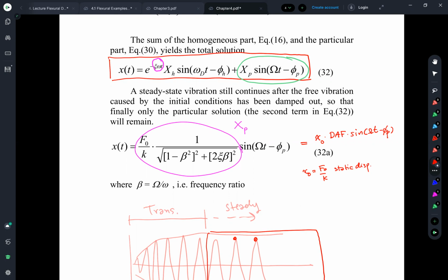I push the truck on the midspan of the bridge and compute the deflection. This is the static deflection. I perform the static analysis only and multiply with this impact factor, and then obtain the total response, the dynamic response, they say.